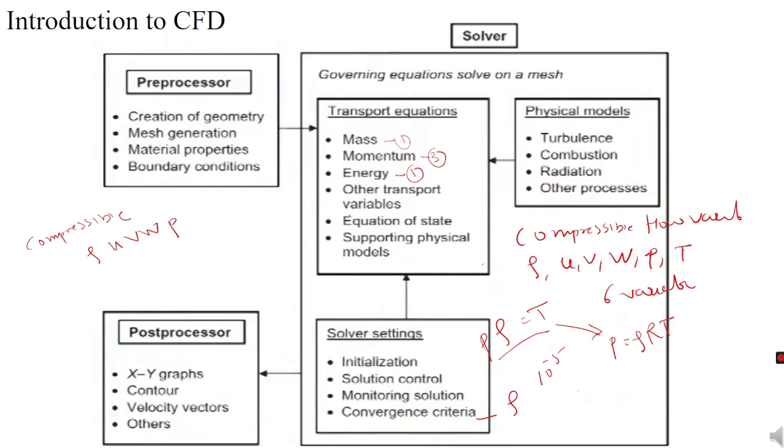Depending on the flow characteristics, you need to choose the appropriate turbulence model. For steady state simulation, popular models include k-epsilon, k-omega or SST k-omega. So Reynolds-averaged Navier-Stokes models, k-epsilon, and the shear stress transport model for more accurate simulation of complex flow, especially involving separation. Then large eddy simulation, LES, or DNS, direct numerical simulation, might be necessary. These types of models help us capture the behavior more accurately.